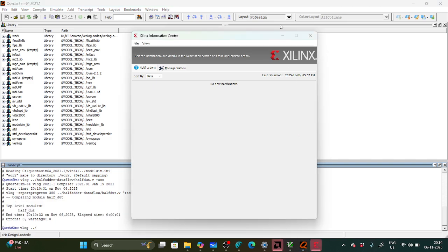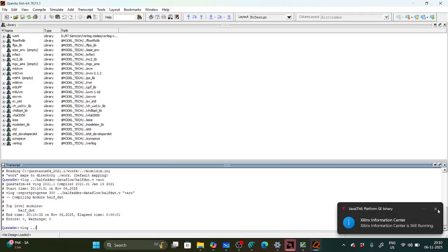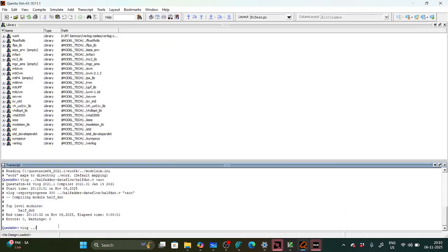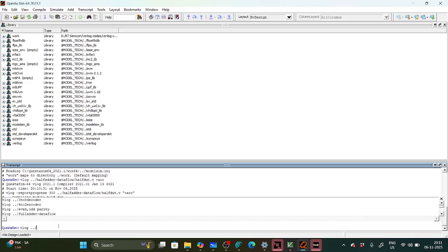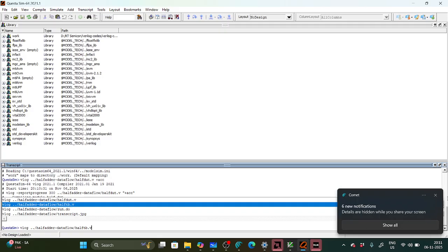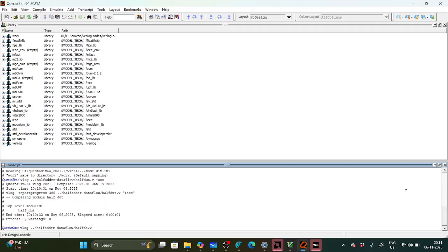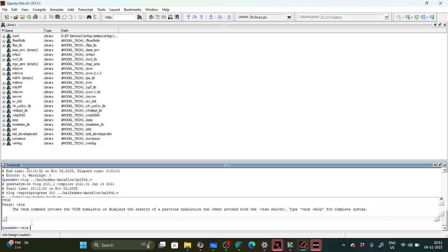Okay, see here. So vlog and slash, what is my file name? Half_adder_data_flow slash, and I need to run the tb file dot v. Okay, vlog dot slash half_adder_data_flow half tb, this one. I got half tb, no? Just copy this, control c, and I need to go for vsim. So paste this.